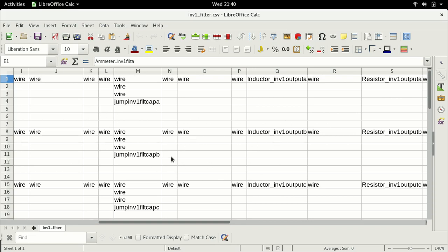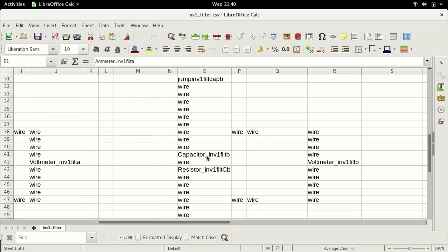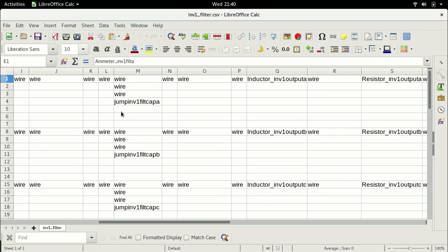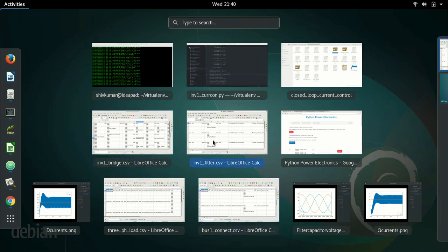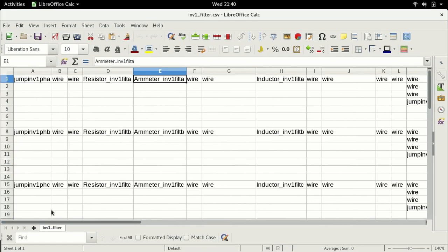It is all incidental. Now in the next lecture we are going to talk about how we are going to regulate the voltages across these capacitors. Alright, because that is the eventual game. This is UPS. We are interested in the output voltage, not the inductor current. The inverter current is an internal variable. Alright, we don't care about that. What we care about is what the load sees, and the load sees the output voltage.